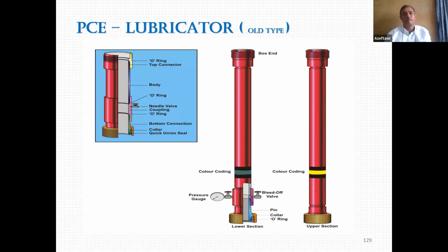But the thread is not designed to withstand torque, while a flange is. So if you finish the rig up, and your rig up is 90 degrees like that, you have no problem. But you're not at 90 degrees. In reality, it shakes during run in hole and pull out of the hole. All you need for a disaster to happen is to be 1 degree off 90.